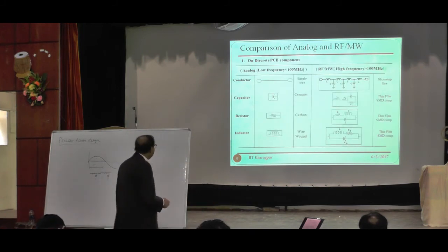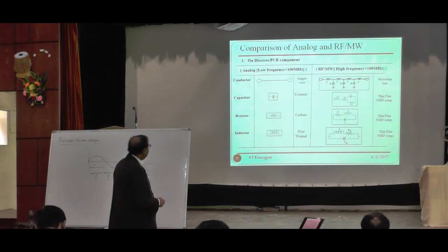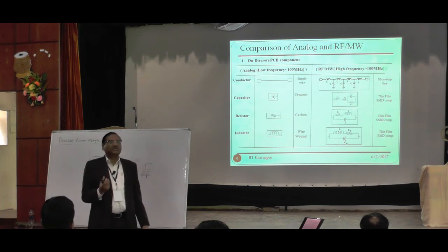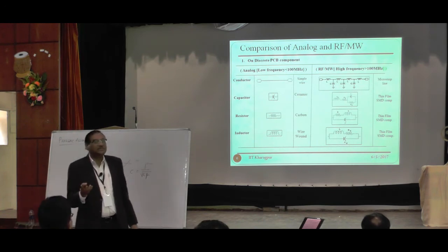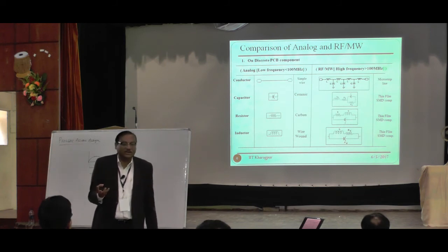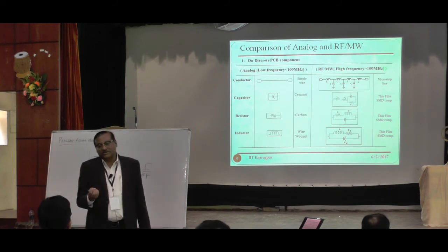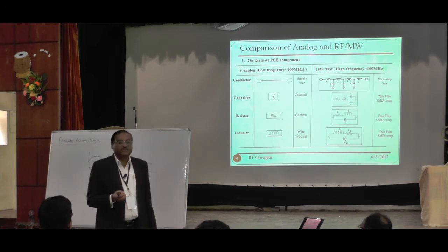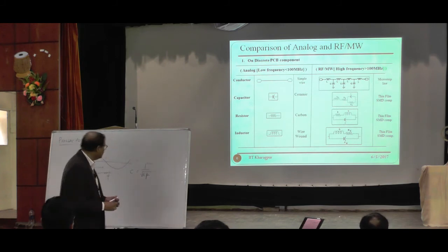So your parasitics of a conductor will be a ladder network of inductors and capacitors, and the capacitors will be a series combination of inductor, resistance, capacitance and resistance, and so on. And the inductor is inductance and resistance in series and the capacitance in parallel. So that will be a nightmare for you, because an inductor is not an actual inductor, it's basically a capacitance. Even some students designing an LNA at 65 gigahertz just tell me, sir, all my inductors become capacitors. It will happen, because if you do not understand the self-resonance frequency, what is the biggest problem here?